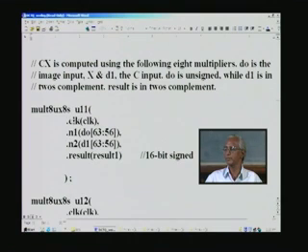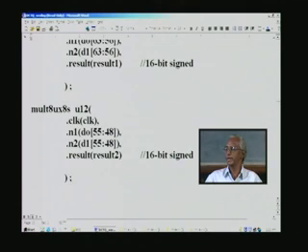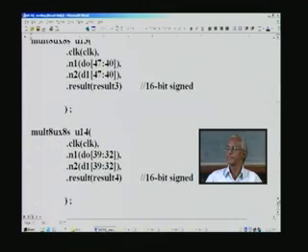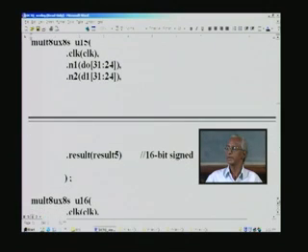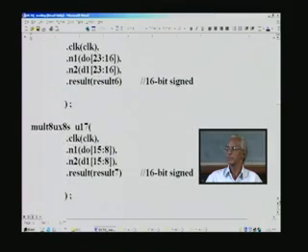So totally it will be 16 bits, and likewise all the 8 multipliers are identical except for the fact that different bytes are used. The next 8 bits are used here in this case, producing result 2, and so on it goes. See here U13, U14, and notice that the bytes are different, progressively less, U16, U17.